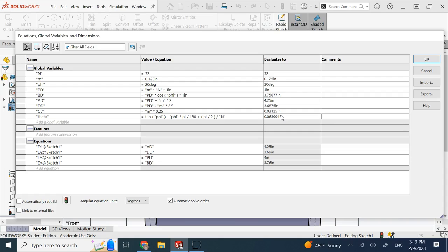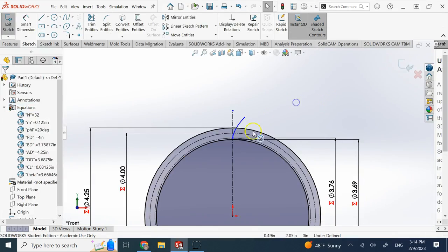If you want, you can convert now this whole thing into degrees, right? So what I can do is grab this whole thing, then multiply it by 180 and divide it by pi. And the unit is going to be in degrees. So I have to multiply it by 180 degrees divided by pi. So the angle is 3.66 degrees or 3.67 degrees. That's the angle that I need to rotate. So that's the angle in front of half of the tooth, the central angle.